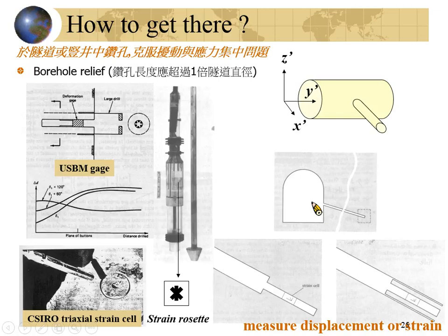In the previous displacement or deformation measurement, we tried to use a strain gauge attached here. We put the strain gauge here, or we make some pins on the tunnel wall and overcore it or undercore it. Then the stress will be relieved, the rock will deform, and I can measure it.